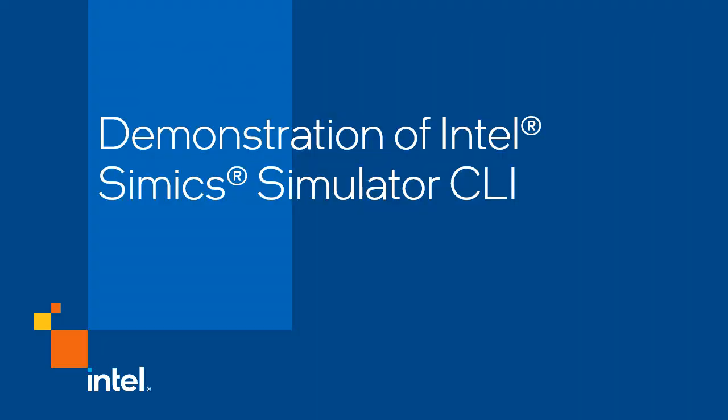This demo includes the step-by-step to set the project and deploy the simulation for the target system, which is Intel Agilex 5 SoC FPGA in this case. These steps are done after the setup for Intel Simics Simulator for Intel FPGAs has been installed in the Linux OS host.